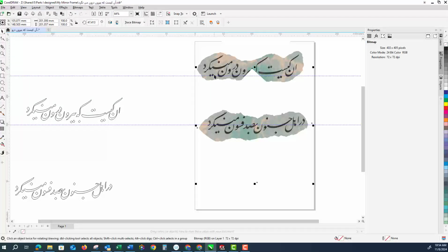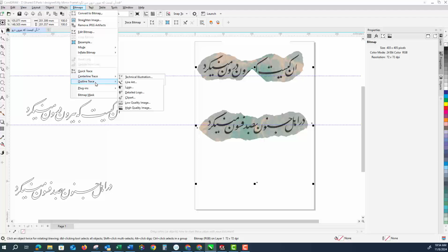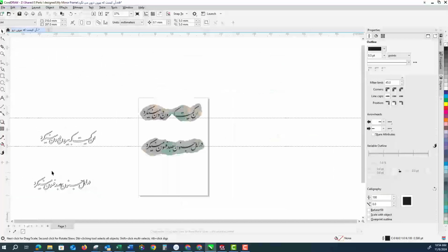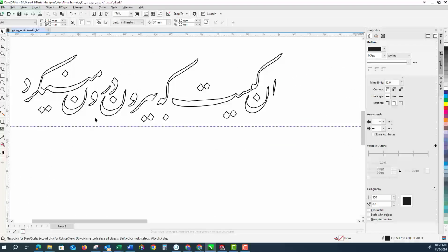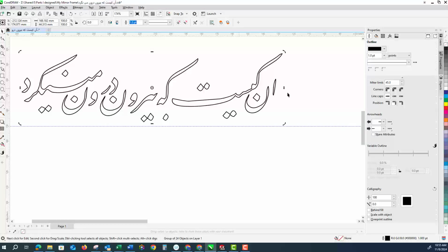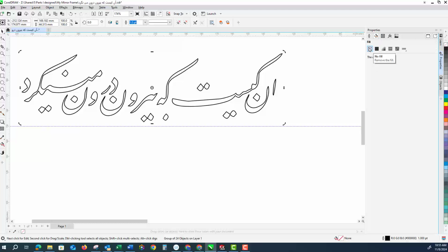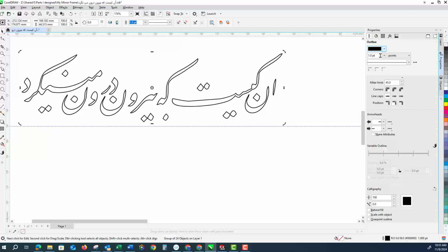The other option you have is Outline Trace. With outline trace, it only detects the edges and an outline contour, which is suitable for a vector to be imported inside SolidWorks. I think I chose outline trace and detail. So this is almost usable. You see that everything here is made of lines, and you also want to turn off the fill, and then just choose a line thickness, whatever, I've chosen 1, and the color black.